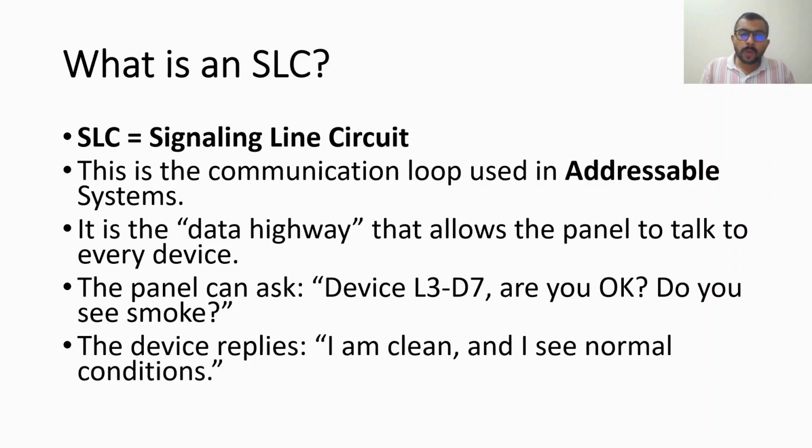In the addressable system, we have come across an abbreviation, which was SLC. SLC stands for Signaling Line Circuit. So what is a Signaling Line Circuit? The signaling line circuit is considered to be the communication loop in the addressable system. It's like a data highway that allows communication between the panel and the device.